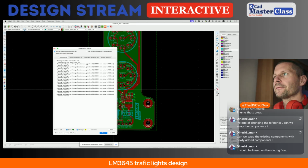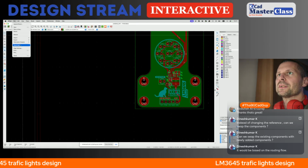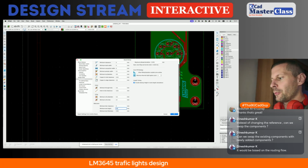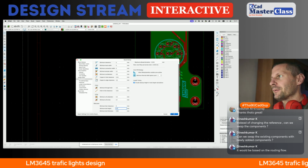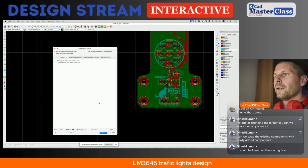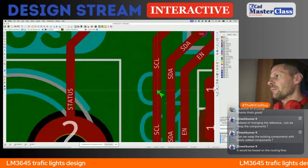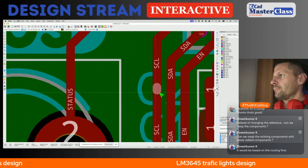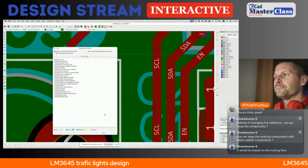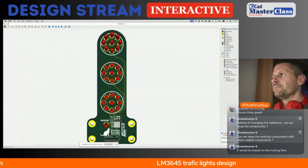12 warnings. Oh, yeah, this is the board setup constraint of the minimal size of the label, which is 0.8, but we have 0.7. Record the DRC. One warning, unconnected end. Okay, this is some more piece of track inside of the track. 0, 0. Okay, how it looks.